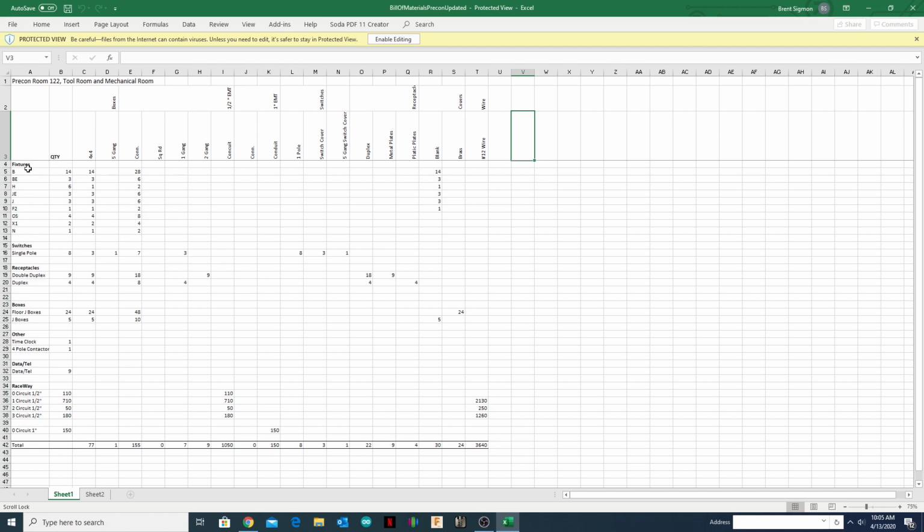You're going to just go through and double check my numbers. These are what we're taking off, and over here is how we're going to build the assembly, whatever it might be. So for the light fixtures, if we were able to look in the room, which we can't because we're doing this remotely, we'd see that above every one of the light fixtures there's a 4x4 box mounted that the whip from the light goes and connects to. So we're going to add our 4x4 box, one for every light fixture.